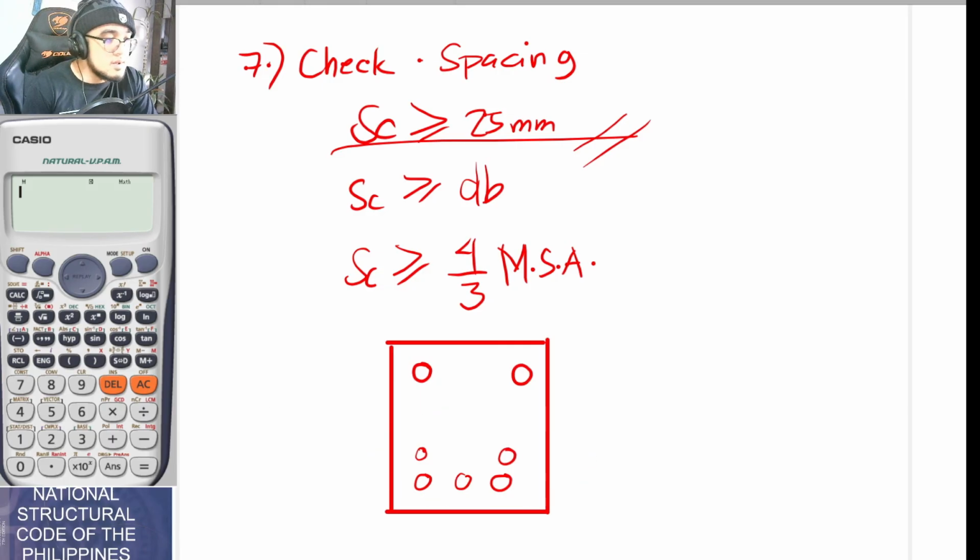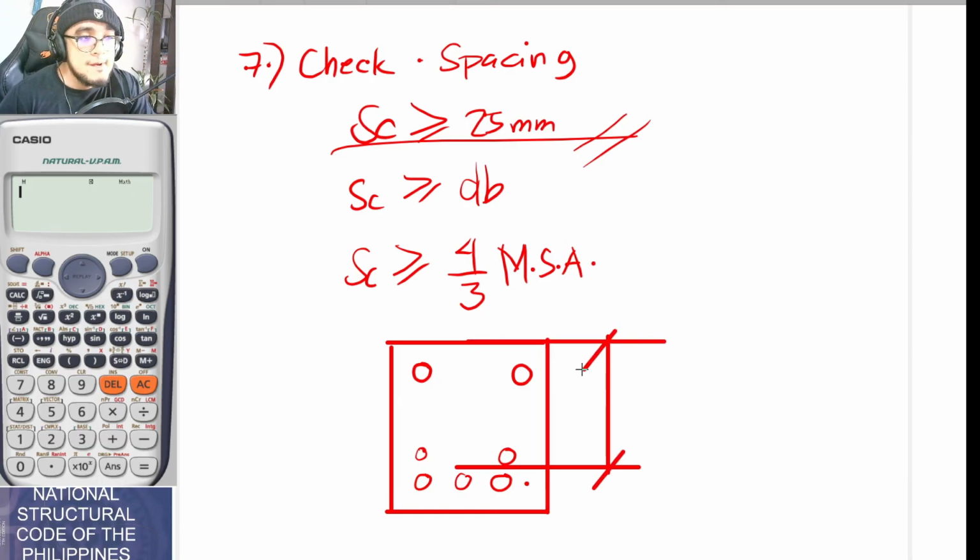However, you must resolve for d since its value will now change. Because earlier, if this was your value of d, that would no longer be the case, since you would be having 2 layers and the effective depth should be measured from the centroid of your steel rebars. So it should be in this particular manner.